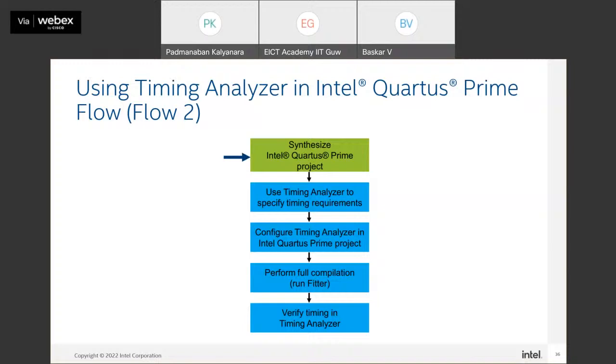When we apply the timing constraints, it is essential to check that the design has accepted those constraints, and that there are no setup and hold violations. We should take that constraint file, integrate it into the Quartus Prime design software, again perform the fitter operation, and ensure that at the end of the fitter the design is not showing any violations, so that we can go to the next step.